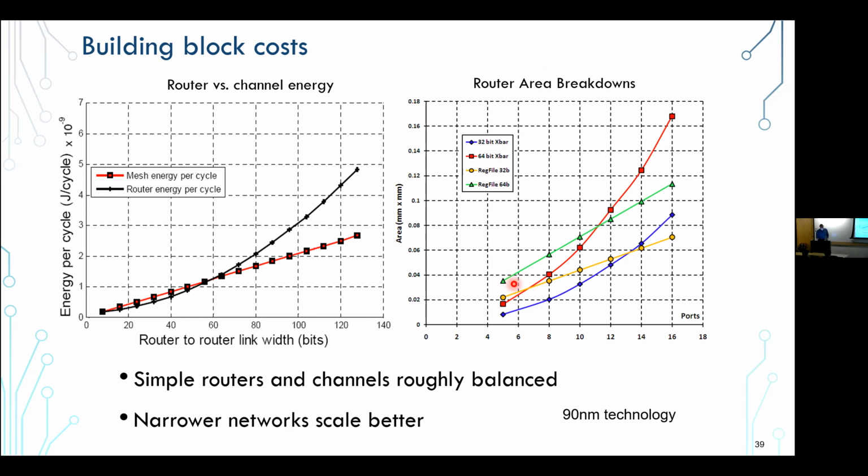And then, of course, measuring some SRAM area, because remember, we have to do both output virtual channel buffers and input virtual channel buffers. So it's useful to understand how much of the overall area of the switch goes to the actual switching and how much it goes to the buffering, right? So you see that buffering is comparable in the large number of ports. It's almost a wash, and then it goes a little bit more for the larger crossbar here on top.